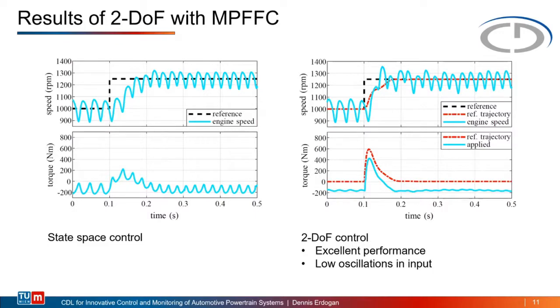As you can see, there are a lot of oscillations in this engine speed, and this is caused by the engine itself. Ideally, the feedback controller would just simply ignore that. On the plots below, we see the input signal, which is the dynamometer torque. And as you can see here, they are oscillating quite a lot.